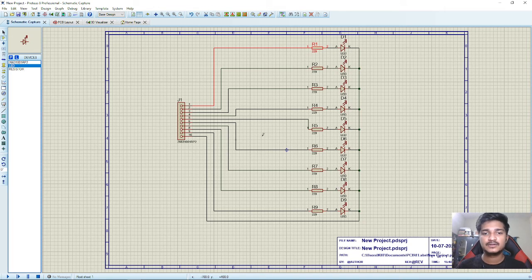Okay, so I think I have cleared many of the doubts of Zaradros. The one thing which I would like to mention here is he was working with 10 LEDs and this specific jumper, or male header to be specific, but I would like to just correct him: if you are using 10 LEDs, you need one extra pin for the ground connection.